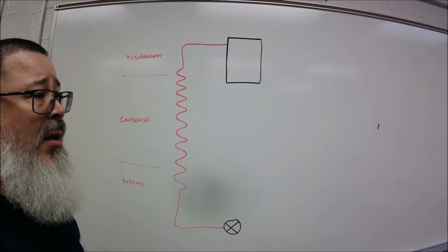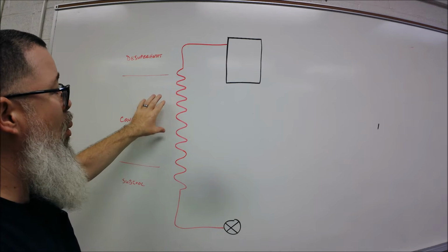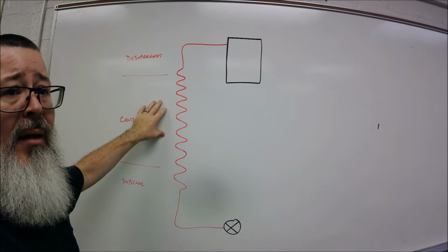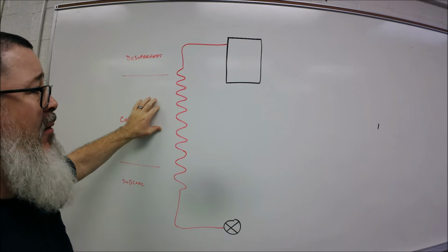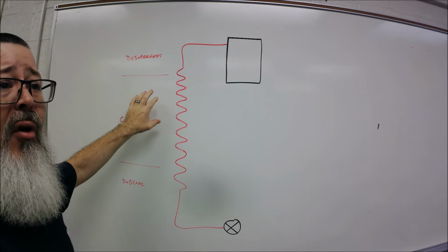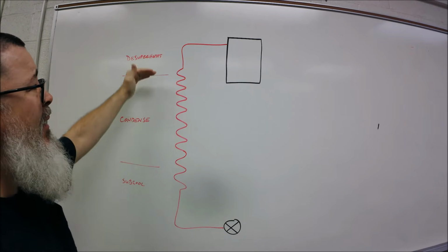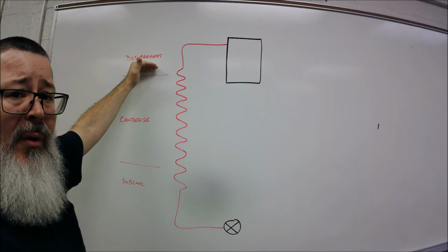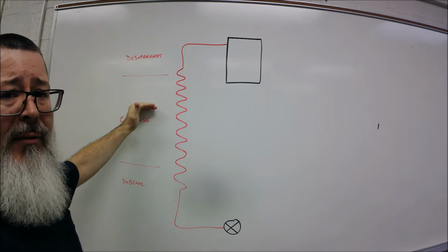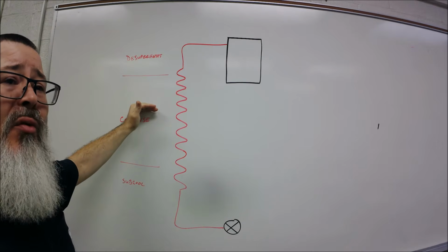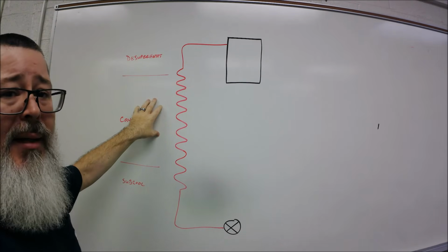The first little portion of the condenser coil is to get rid of the superheat, because whatever pressure our condenser's at, we'll just say it's 340. That's about a 105 degree saturation point for R410A. All right. We have to get that 140 degree vapor down to 105 degrees, right? We have to remove that extra sensible heat, that superheat, so we can condense it, right?